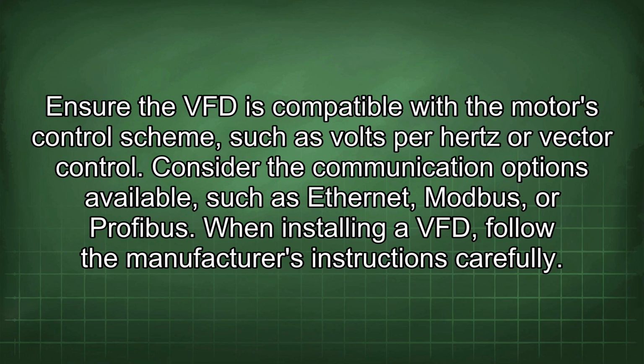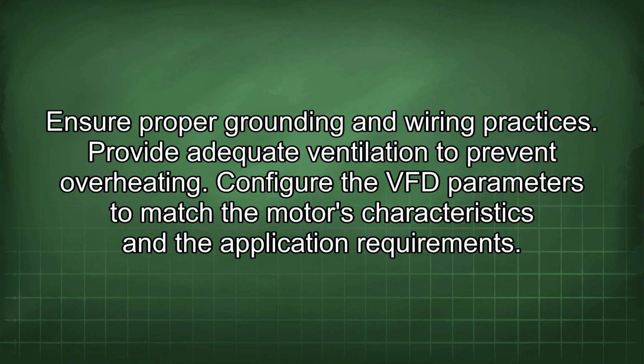When installing a VFD, follow the manufacturer's instructions carefully. Ensure proper grounding and wiring practices. Provide adequate ventilation to prevent overheating. Configure the VFD parameters to match the motor's characteristics and the application requirements.